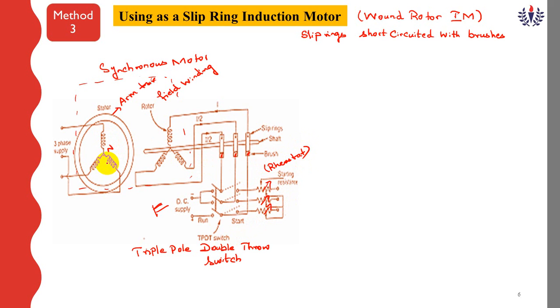When the stator is excited, then the motor starts as a slip ring induction motor. Now by using this resistance, the starting torque will be very high. Now what we have to do? We have to reduce this resistance value. Based upon the movement of this resistance, we can adjust the speed to synchronous speed NS 1500 RPM. Here also, these windings are shorted.